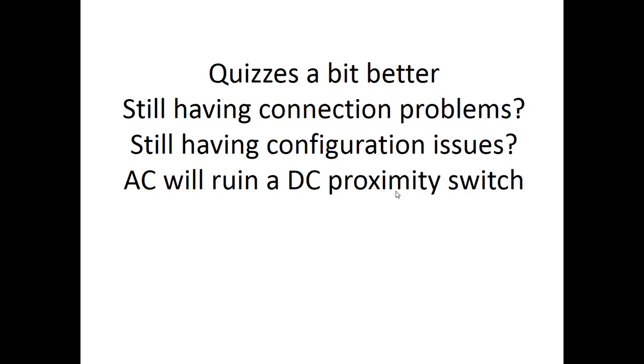Quizzes: you should have gotten a quiz back, and if you have any questions, ask the professor about that. Are you still having connection problems? So we did sinking and sourcing last week, and you should know that we were grounding out our input modules and bringing voltage to our output modules, because we were sinking input modules and sourcing output modules.